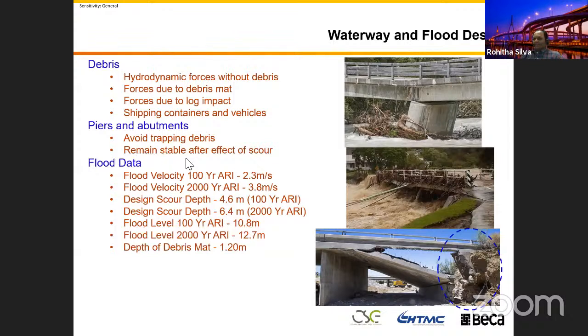And then they must remain stable, because if there are massive flood flows, I think the main problem in the bridges is the scour. A lot of the silty material will be washed away, and because of that scour, the pier length will be increased, and because of the flood force, there will be a situation where the bridge will be unstable. You need to make sure that you capture that in your design.